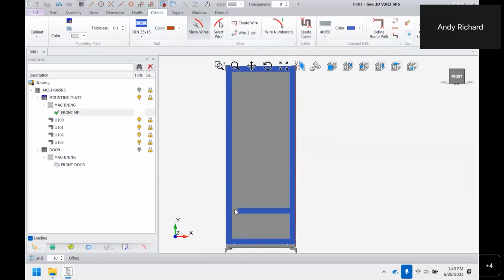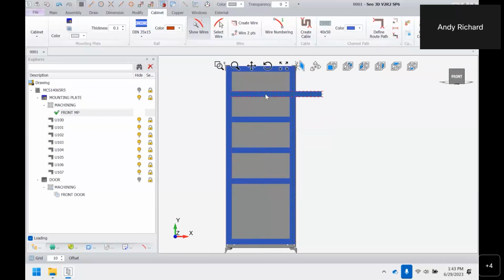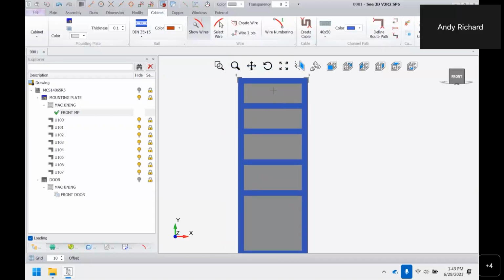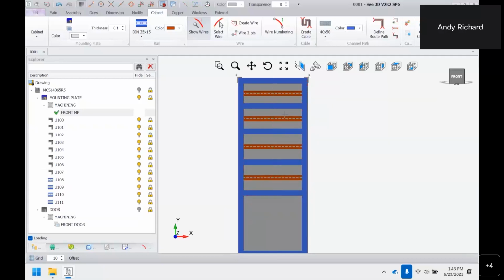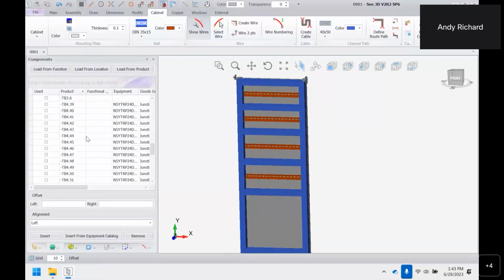So with all of these, I can just right click and I can place each of the parts in sequence. I can also offset a specific distance. So if I wanted to offset 180 millimeters up, I could do that. So you have exact placement. You also have the automatic grid snapping. With the DIN rail, I'll then come in here, populate these. And so now that I place some parts, I can start building actually my cabinet.